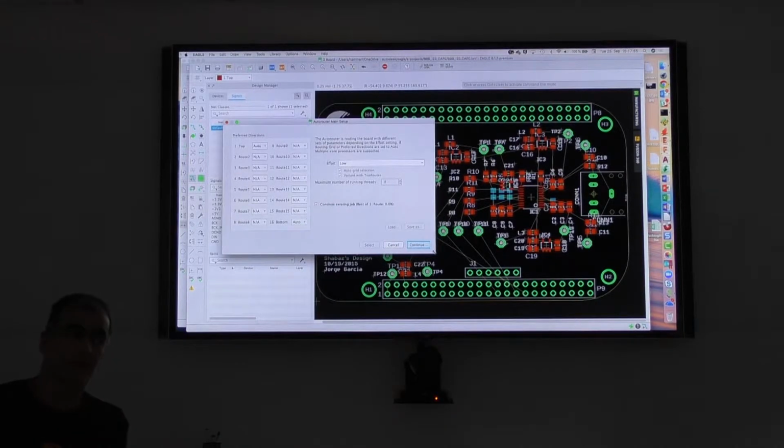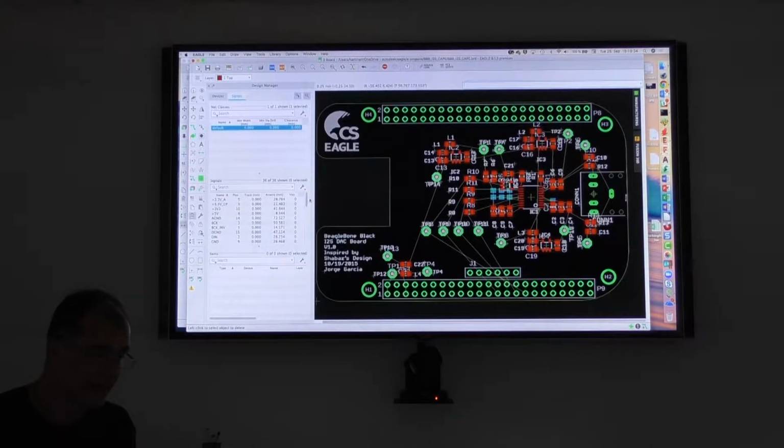You could use the autorouter as a tool to evaluate your positioning of the components. If I start the router and in, let's say, 2 minutes I have a result of 20%, then it's probably pretty bad. I can try to rearrange the components, do a second try. If I have in 2 minutes 70 or 80%, then it's better. So you can estimate maybe this could be better.